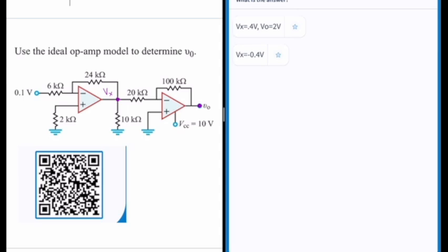So you could use just a non-inverting. When you get to control systems, if you take your control system class, you learn that you actually have a frequency response, and you get two poles that have each amplifier. And that's going to affect your overall control system. So it's more about controls and how many poles and zeros you create.